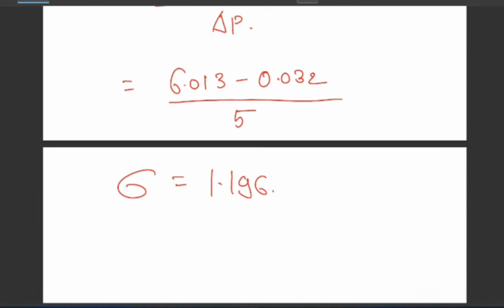This tells us the valve is operating with a downstream pressure substantially above vapor pressure. It is above the vapor pressure, not at or equal to it. There is a big difference between the vapor pressure and the operating pressure. That means there is no cavitation.